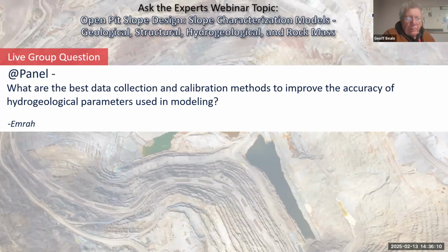And you can't beat piezometers. Piezometers are the fundamental control. If I think I said that, when I go into a site, the first thing I look at is all the water levels. If the water levels are all similar, we know the hydraulic system is connected. We know it's going to be quite permeable. If the piezometer levels, the water levels are all discontinuous,